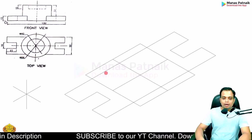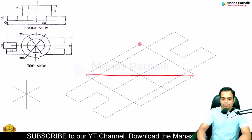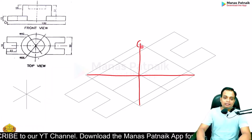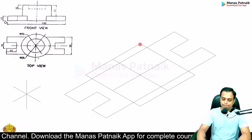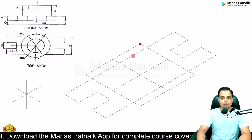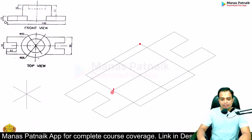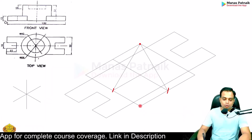Now, whenever you do this construction, there is a larger diagonal and a smaller diagonal. It is the smaller diagonal's corners that we are interested in. So we are talking about these two corners. Choose any one to begin. The opposite two sides will have these 2 points as the centers. Connect. Similarly, choose this corner.